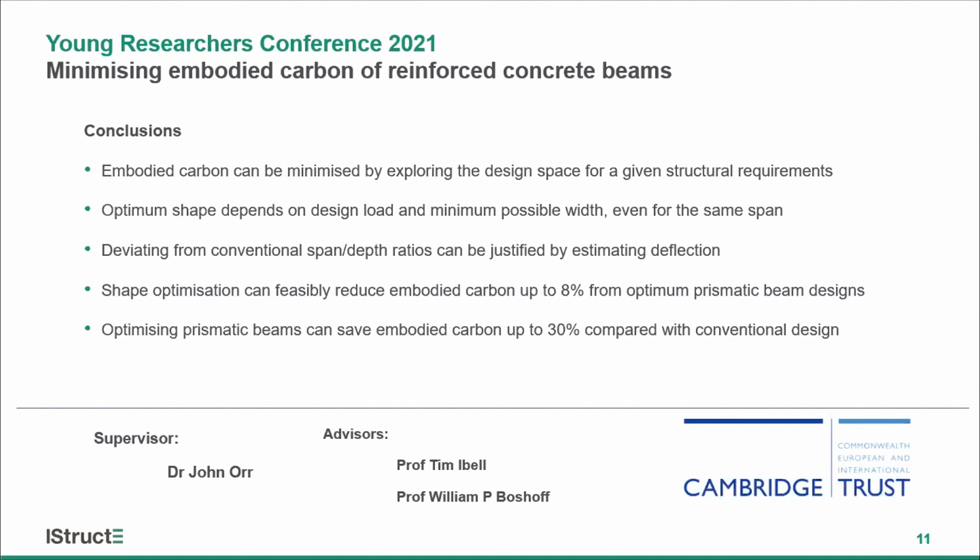I would like to say, rather than challenges, we would need the know-how about the detailing of the formwork, because we can have very good precision with the flexible fabric formwork, but we have to know how it would work, how the fluid pressures would work, how to arrange the reinforcement, and then how to arrange the fabric as the formwork. I think if we know how to do that, we can adopt these techniques safely in construction as well.